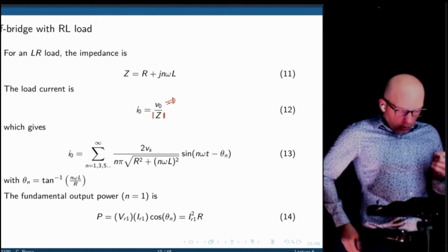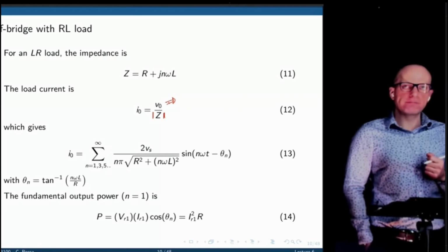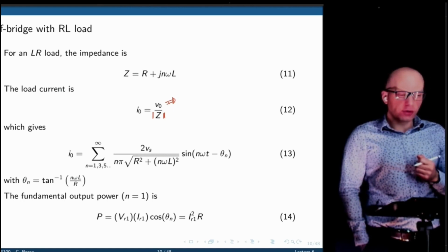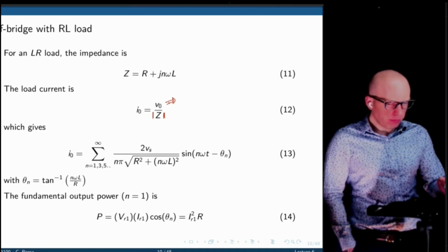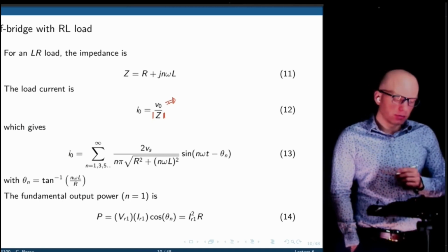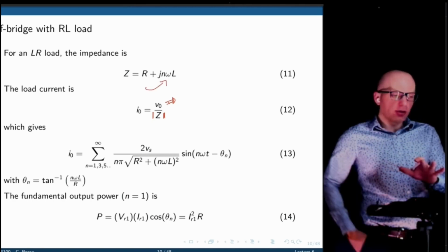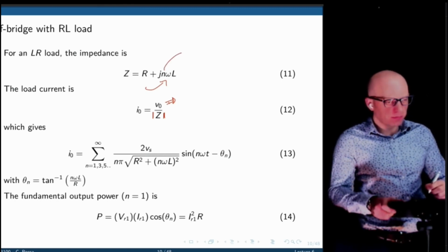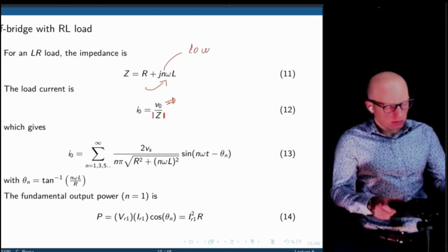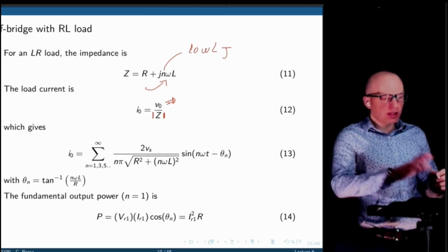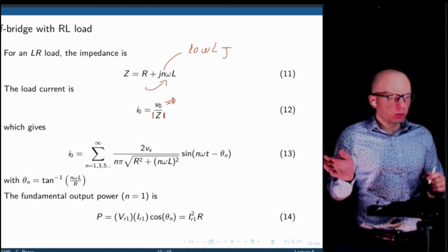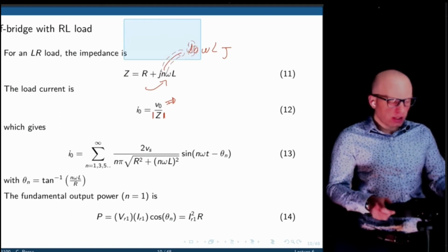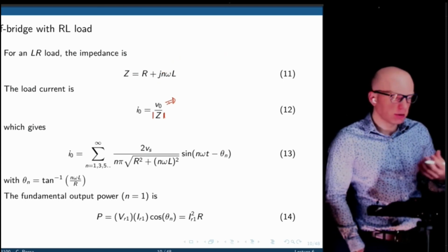Right? Question? Yeah. As the frequency increases, doesn't the impedance just become R? As the frequency increases, the inductor will dominate the impedance. Actually, as the frequency increases, the effect of R will be negligible compared to the effect of the inductor, because N is increasing. All right, so let's say to the 10th harmonic, we would have something like this. It's 10 times higher than what we started with in the first harmonic. So the higher we go in frequency, the more impedance you have in the inductor. All right, so it's actually the opposite. Then the effect of the inductor will dominate the impedance.